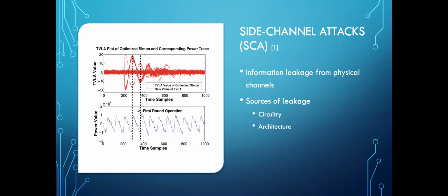circuitry. Basically, the type of attacks that are carried out on this leakage source are CPAs, which are correlation power analysis. CPAs basically rely on a power signature of a particular set of gates from the circuit, and these can reveal sensitive information with regard to like the Advanced Encryption Standard or private circuits, secret keys. And of course, you never want to reveal information regarding that.